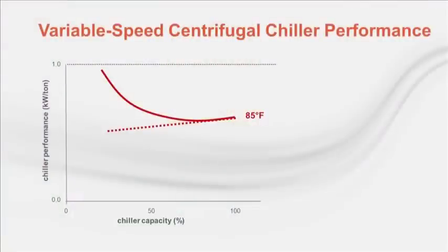For variable speed performance, we will view charts that have the same arrangement of terms we used earlier for the fixed speed compressor. We start by looking at chiller kW per ton performance trends compared to the ideal part load performance targets. Shown here is the 85-degree condenser water temperature load curve. It doesn't look much different than that of the fixed speed chiller, since full or nearly full speed is required to achieve this load curve without surging.